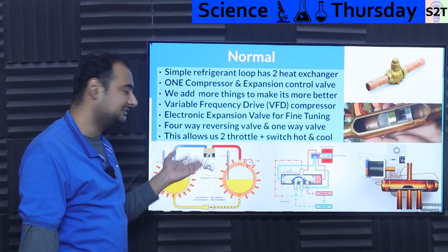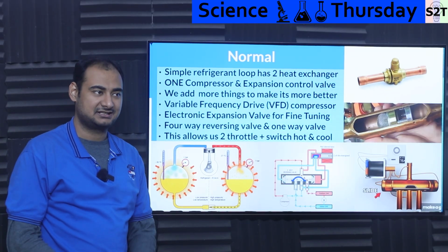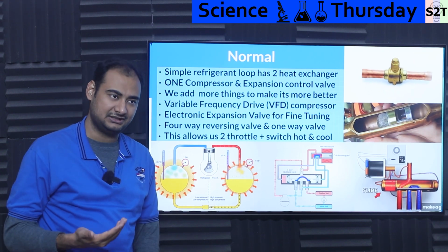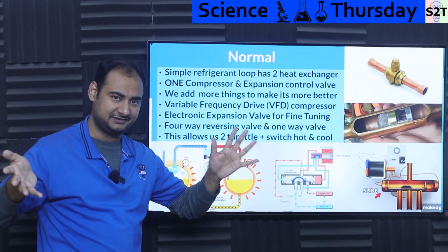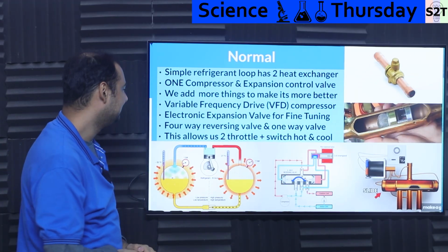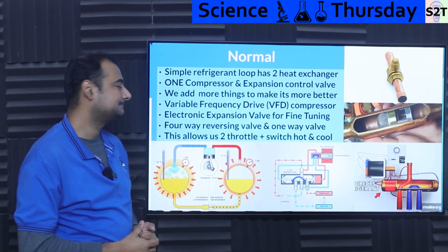Why is that? It does not have any throttle. It's just on or off. So that creates a lot of oscillation. More than good enough, especially because your room air acts like a low pass filter. It's like a filter scenario. It has so much mass, it's buffering it.